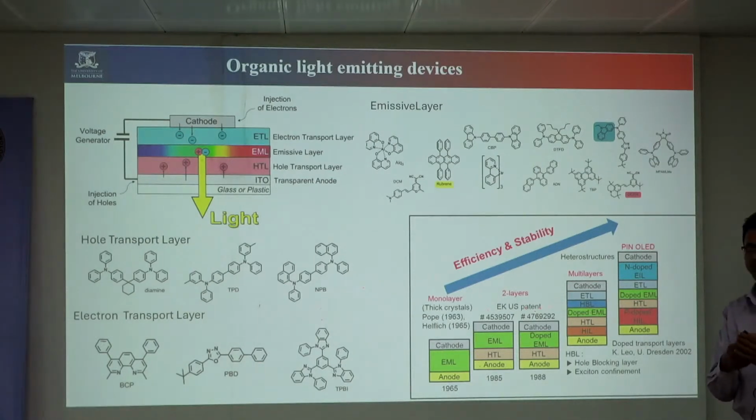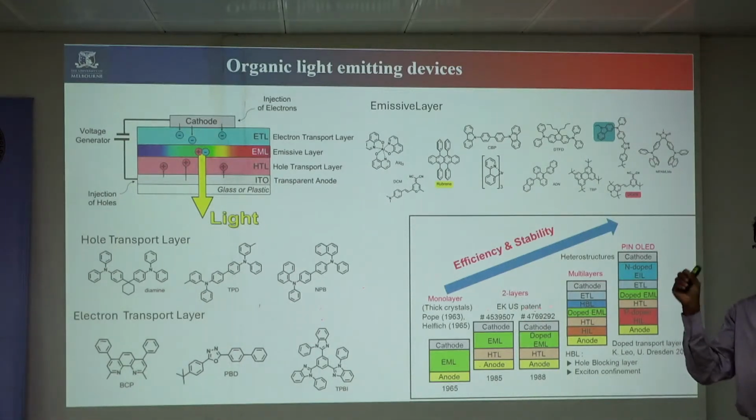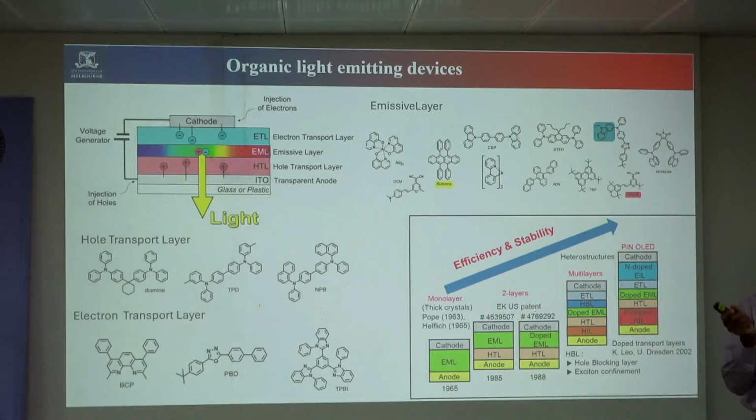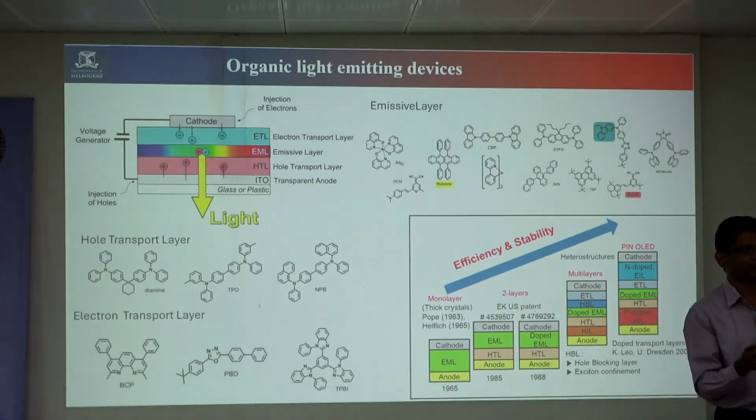For example, for P-type we inject boron, because boron has only 3 valence electrons, so one electron becomes a vacancy. For creating N-type silicon, we inject phosphorus. Silicon has 4 electrons, phosphorus has 5. Out of 5, 4 are bonded with the silicon and the remaining 1 is free. So we get 1 free electron for 1 phosphorus. Like this, we can create N-type or P-type material.